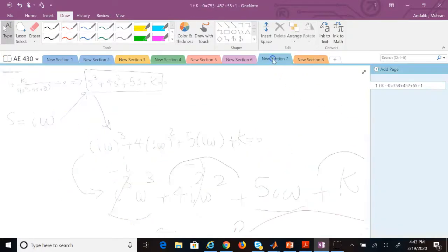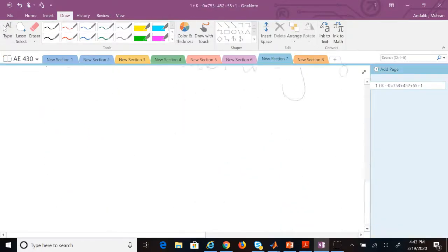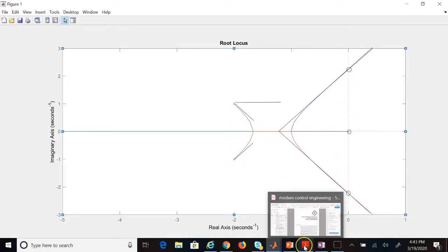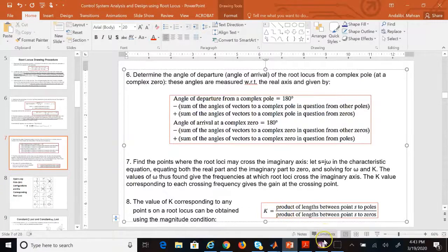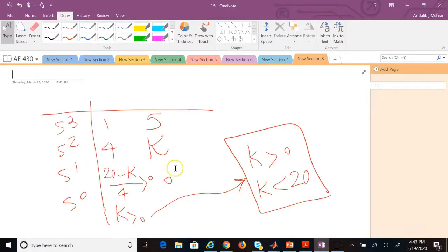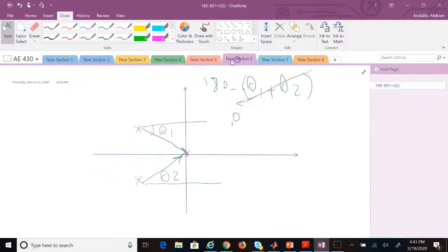By the way, if I go back to this one here, I better correct it. I should remove this equality here as well. Why? Because if I do so, then the pole is here, which is still on the imaginary axis and means sustained oscillation. So I should keep avoiding the imaginary axis. It should be perfectly on the left-hand side. So the condition for stability in my case is K between 0 and 20, which I can find from Root Locus or Routh-Hurwitz, from either of them, right?